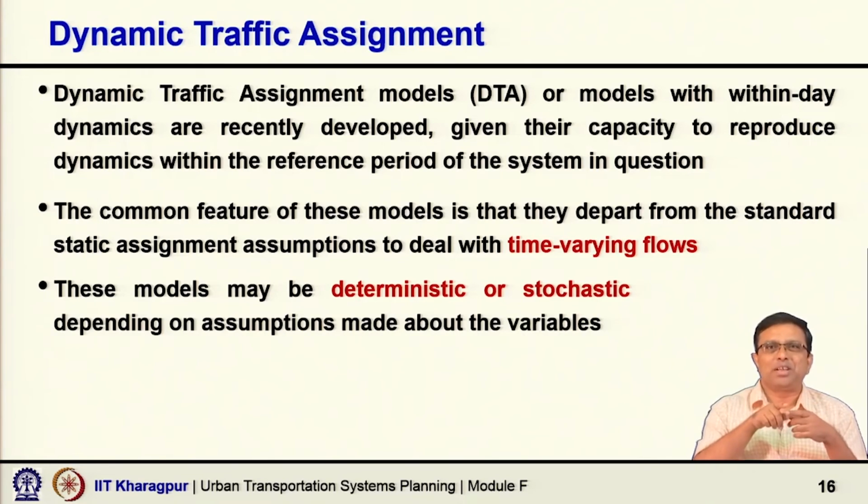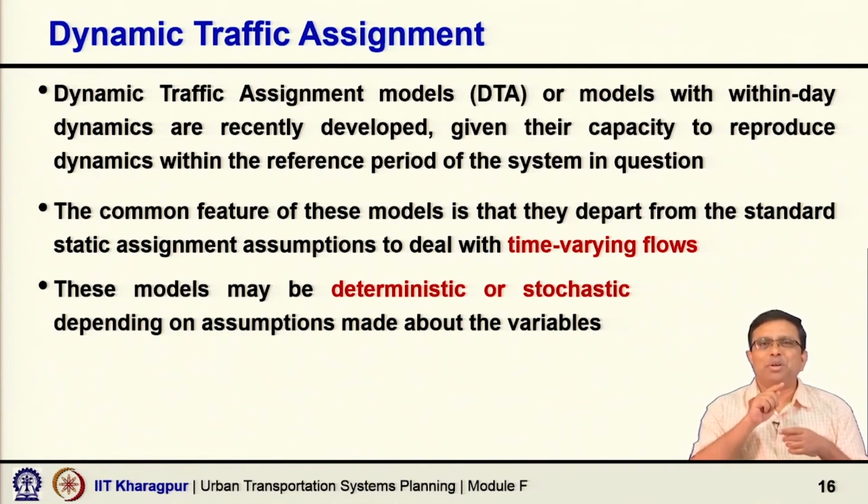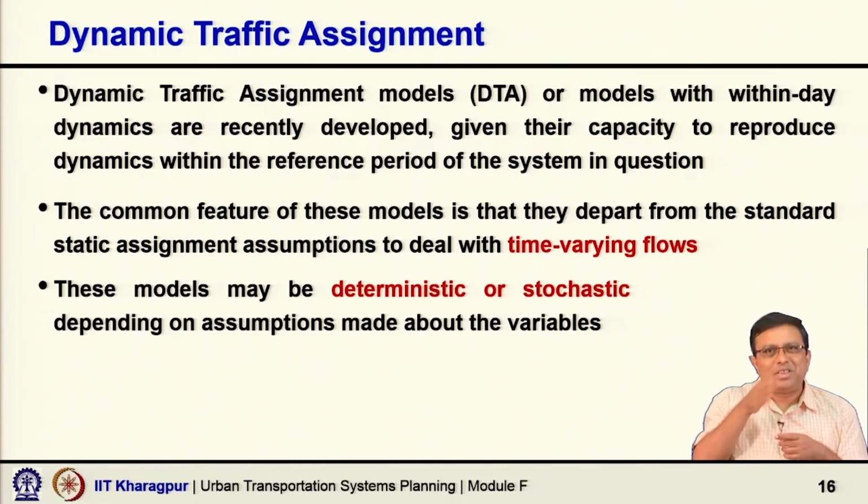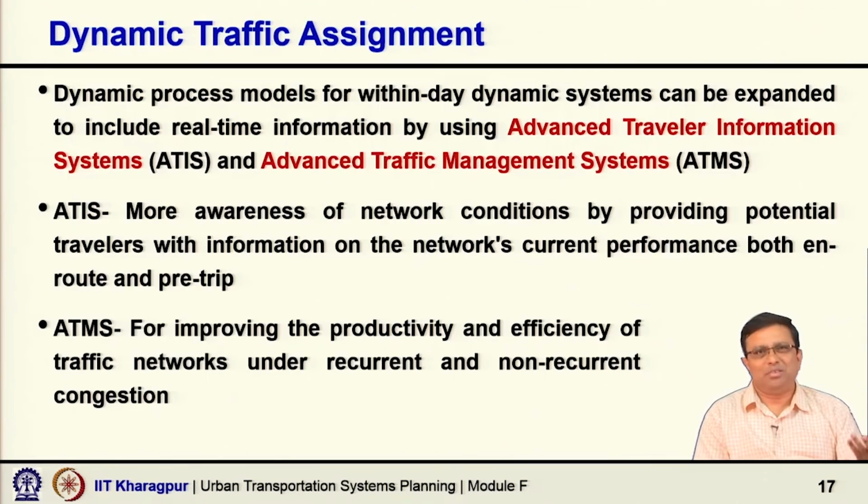Now, this is a new dimension, function of time. Demand itself is a function of time. So, everything we have done, we cannot do one time, but things are happening again and again. Every delta t time, the decision making is happening. Once you call it dynamic, you are focusing on the time dynamics, time variant flow. Then for assignment, you have options: you can consider deterministic assignment or stochastic assignment, whatever your assumption is, you can do both.